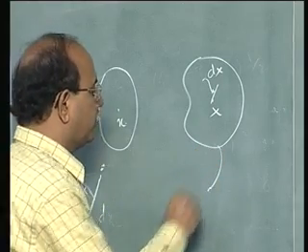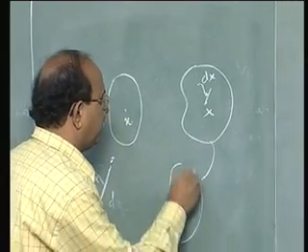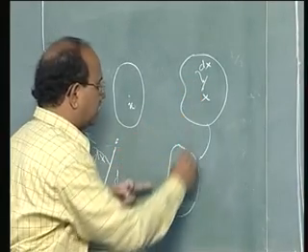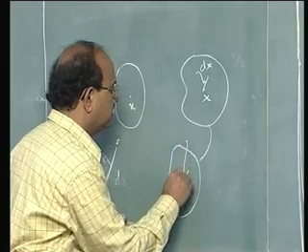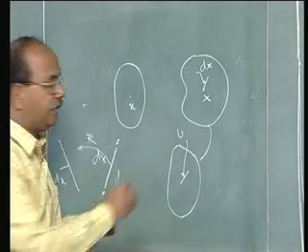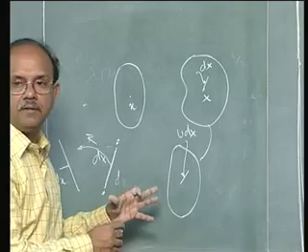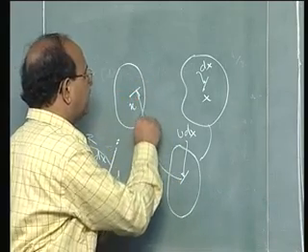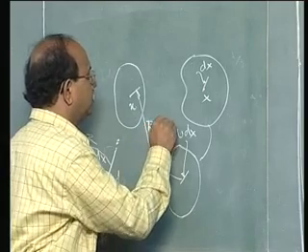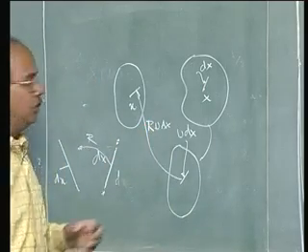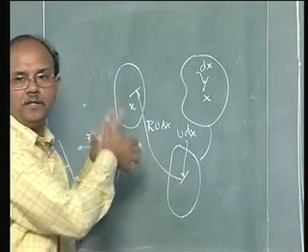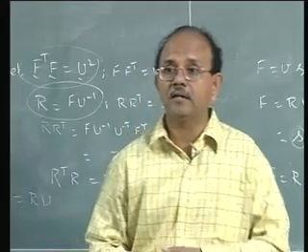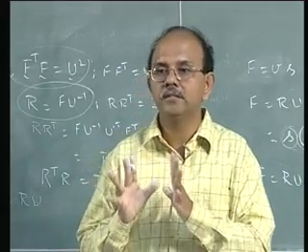This undergoes a transformation first to a body like that, so that dx now becomes U dx, which is the stretching part, and then that gets later rotated from here to here, so that becomes R U dx. So there is a stretching first followed by rotation. If it is VR, then it is rotation followed by stretching.